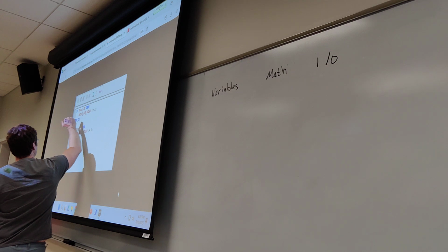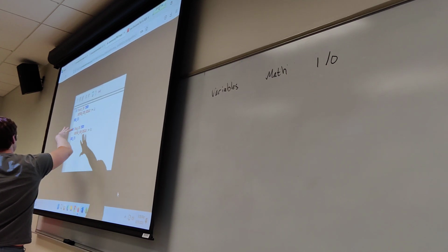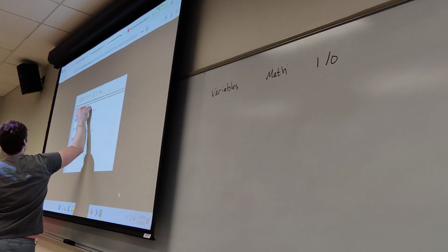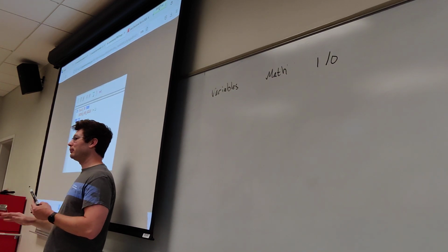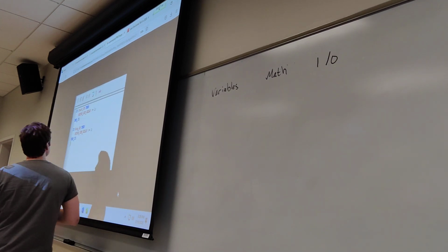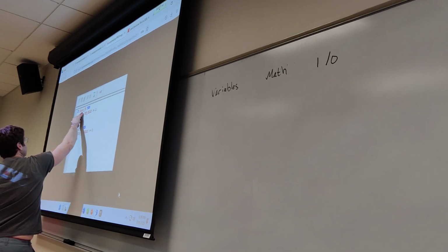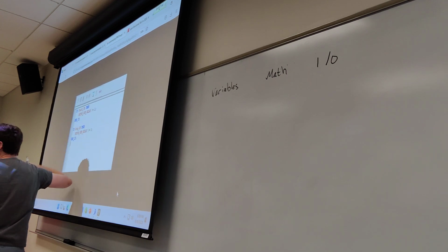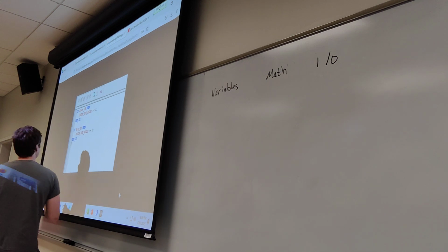What happens is when we step through this code and imbue meaning in it, we use English to establish logic, right? If this, then that is literally something that we can write down and really get like 90% of the behavior of our program. Like, if this is happening, do this. And this is how, for example, we can take an input, evaluate if it's high or low, and then do something accordingly. Is our switch on or off? Is our sensor reporting high or low, right? And then turn a motor on, turn a siren on.